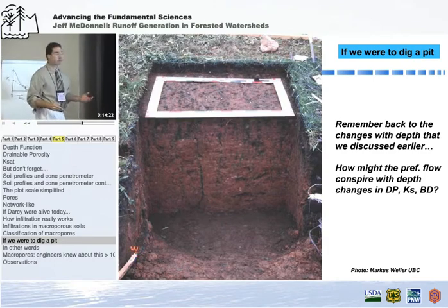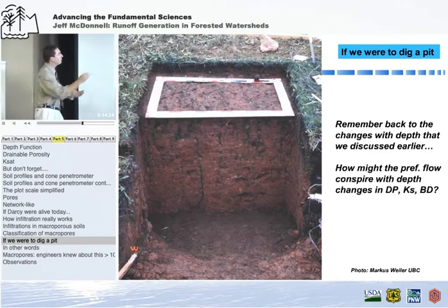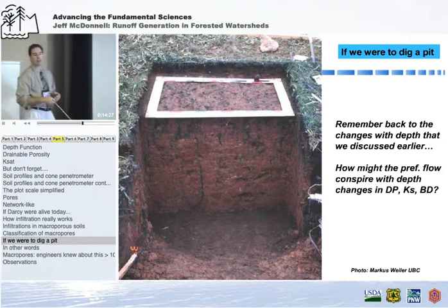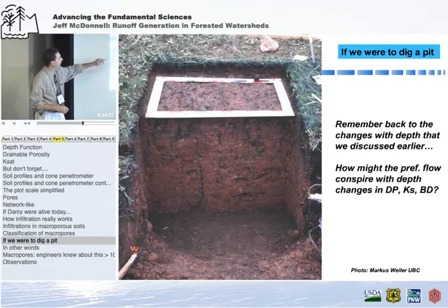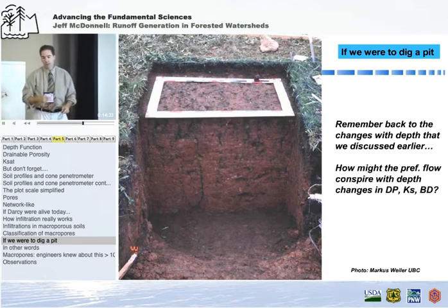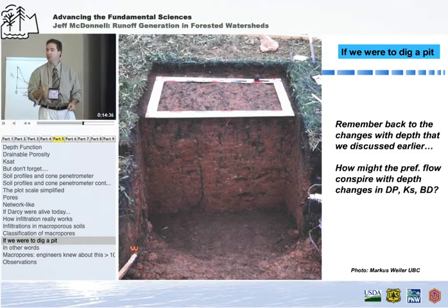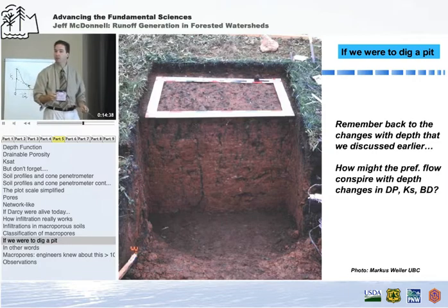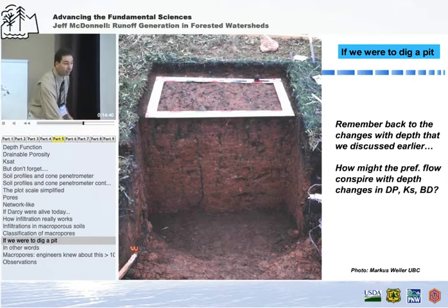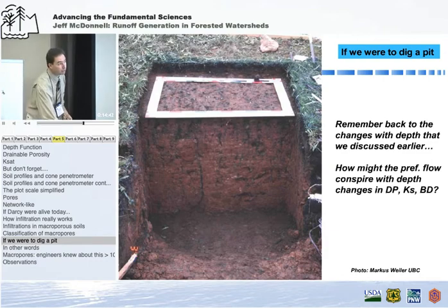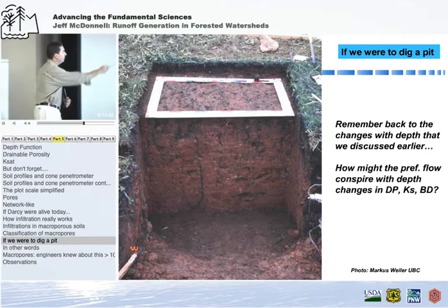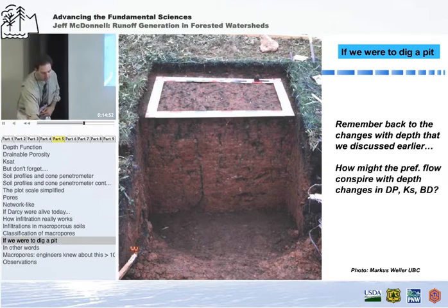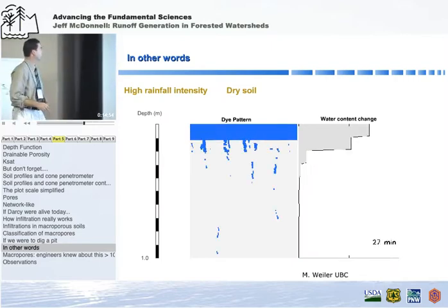This is especially true for, say, a suction lysimeter. You're interested in, say, flushing of dissolved organic carbon or nitrate at your site. And you put a suction lysimeter at different depths through the profile. You're quite likely not sampling the mobile water that's contributing to the flushing on the time scale of an event with that kind of sampling regime. You might be getting a good representation of the soil water end member between events, but what's happening during events is really through these preferred flow paths.